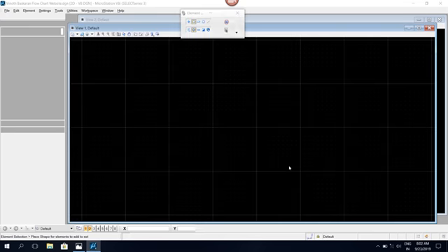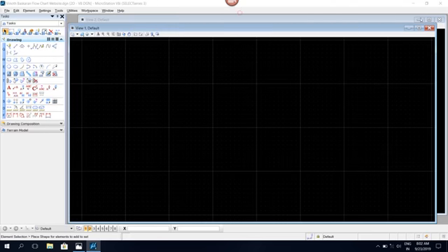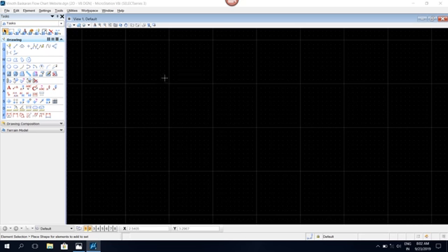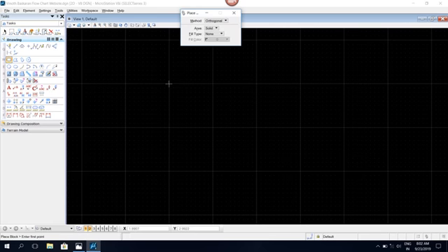Open. Now I am going to create the rectangle with the dimensions. It's a shape. To draw a rectangle you have to choose the drawing tool palette. In the drawing tool palette you have different options. In the option which starts with W, you can find the rectangle shape. The name is place block. You have to choose place block.